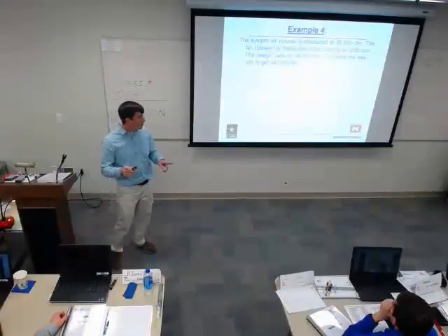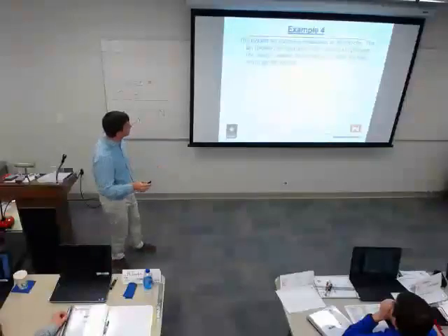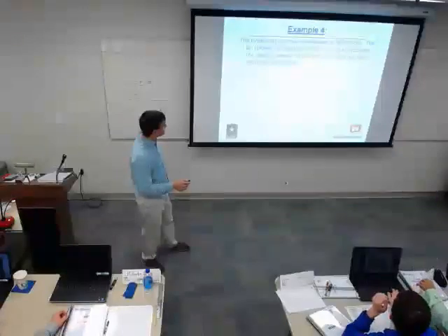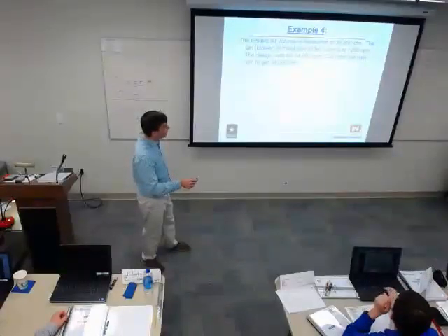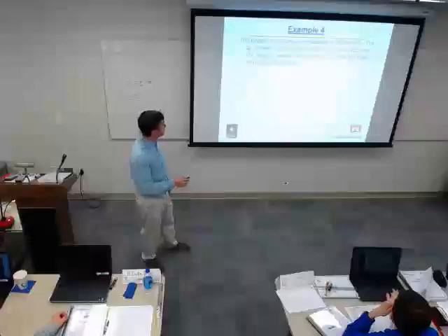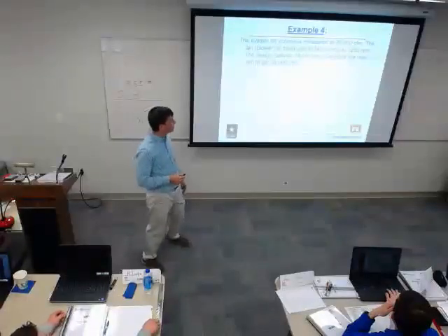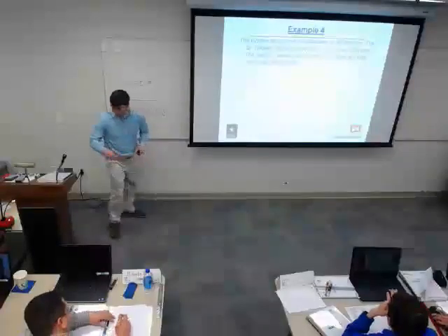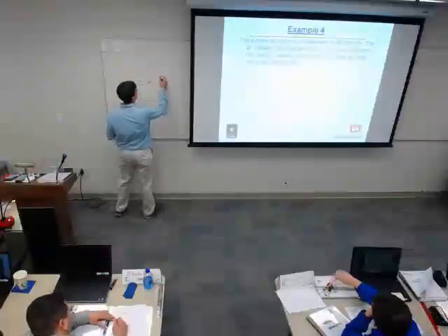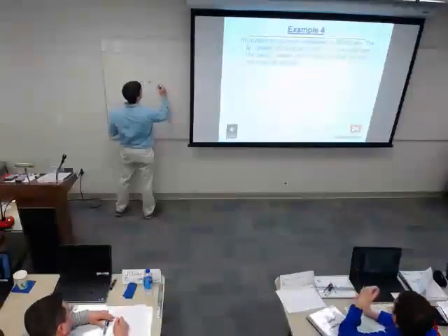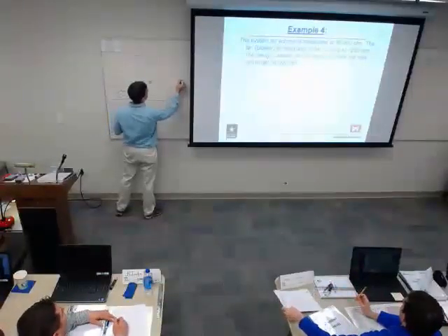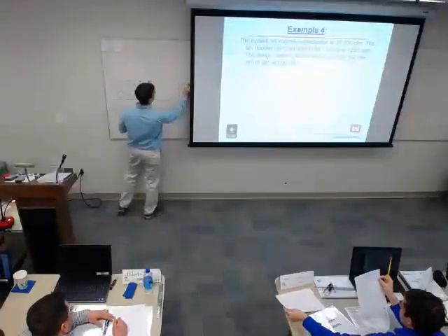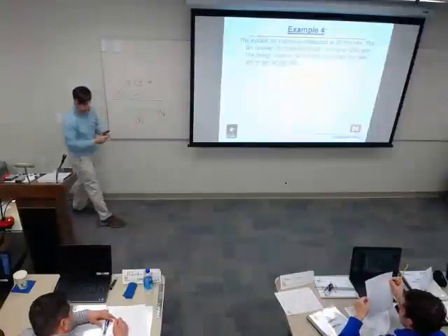All right, here's an example. Please don't look ahead. I'd like you to walk through this. System air volume is measured to be 30,000 CFM, and I measure my revolutions per minute at 1250. I want to get 34,000 CFM. So I'd like you to walk through that calculation. Remember, it was RPM2 over RPM1 equals CFM2 over CFM1.